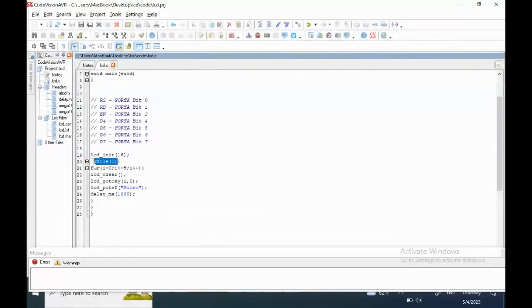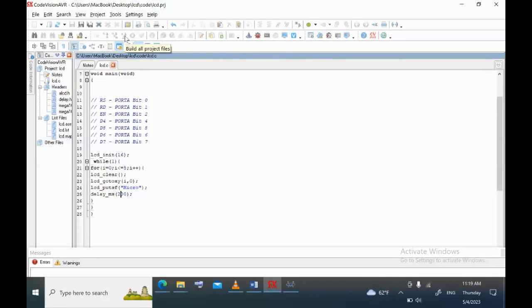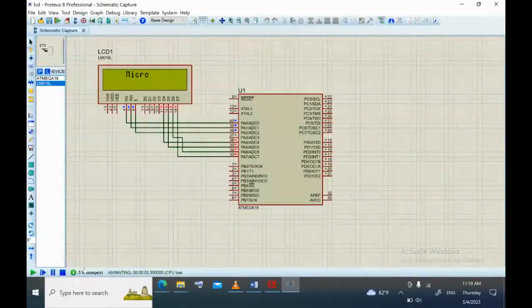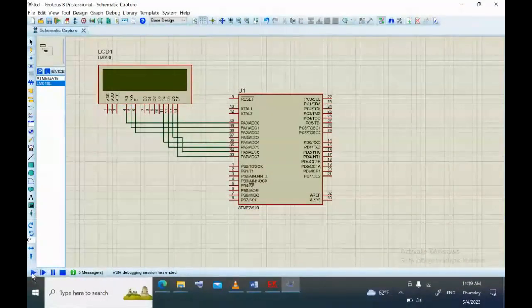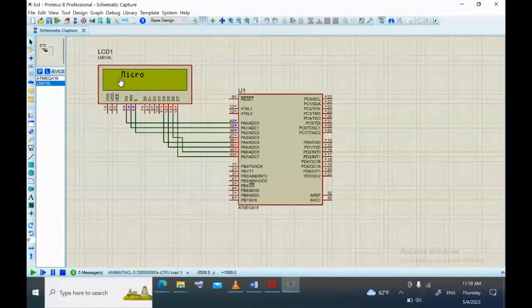But be careful, while one includes one curly brace opened and one curly brace closed. So we can have this moving with high speed, I choose 200 millisecond instead of 1000 millisecond, and I compile the code again and go to my Proteus, and you can see what happened.